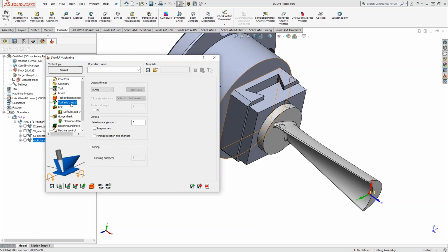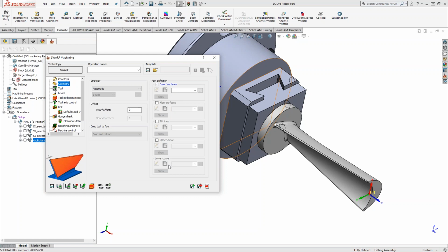It's one that every time someone asks about 5-axis trimming, I show this one. Also, the simultaneous one that I was talking about, because you can line up the parameters on that one to do it, but this one automatically understands you're going to use the side of the tool. And you can see here in the tool axis control section, there's not much here to really control the angle of the tool, because it's all driven by those surfaces there. So this one is purely only for side of the tool doing like Kevin said, either a trimming or you're doing some sort of swarf cut on a blade or something like that.